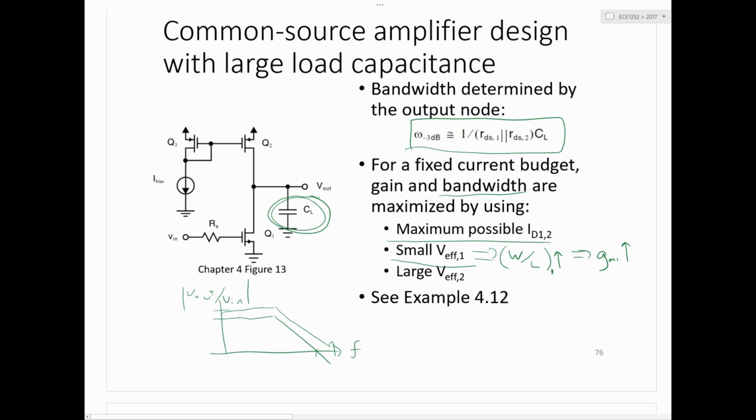And in the specific case that's going to be of interest to you, when this picture really is representing the equivalent half circuit of a differential pair, and that differential pair is part of an op-amp, the front end of an op-amp that's going to be put in feedback, it's actually the unity gain bandwidth of the amplifier that's more important in determining the bandwidth of the closed loop amplifier as a whole.